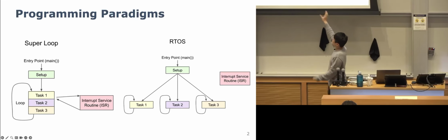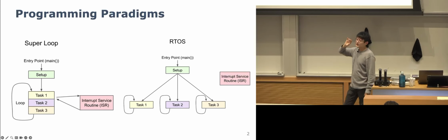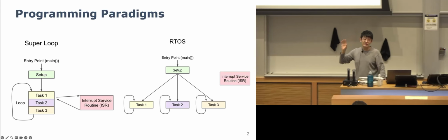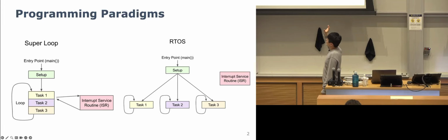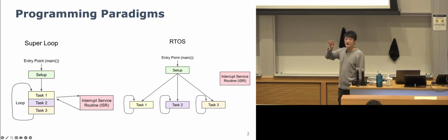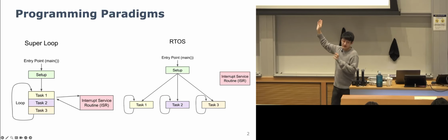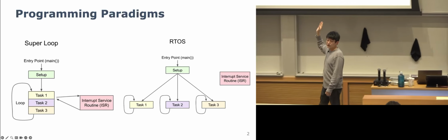But how do they still do this? The idea is that they implement, in software, something like a virtual timer, but in a different way. I think one of the classmates actually mentioned SysTick in previous lectures. They have a software-implemented scheduler that keeps track of the list of tasks and the latest time each task is supposed to be executed.